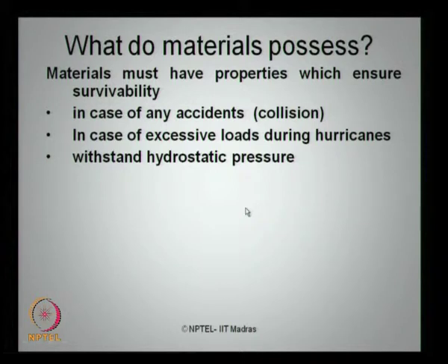For example, land based structures may not have to undergo forces resulting from accidents very often, whereas in ocean structures or offshore structures, collision is considered one of the day to day life loads, because tugboats keep on offloading the fuel from the platform, or the crude oil from the production systems, and there is a high probability that these vessels may touch or rub upon the members of structural systems.